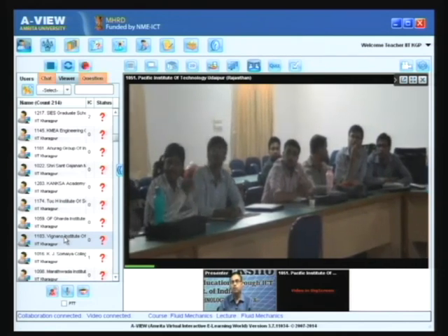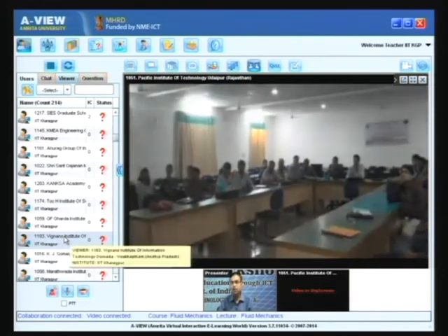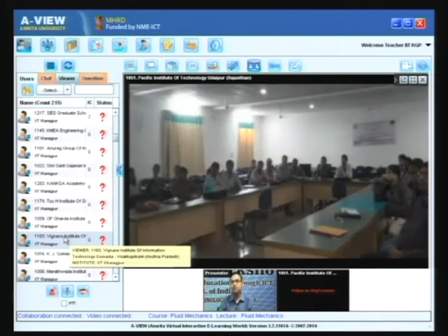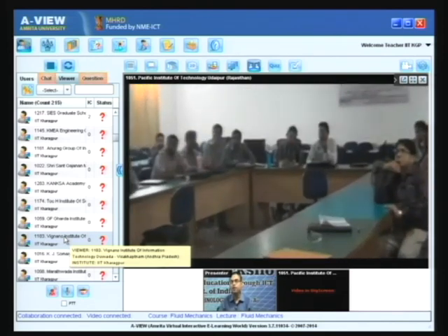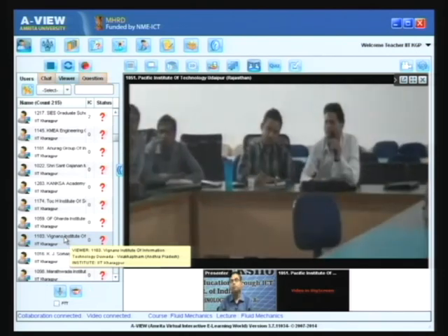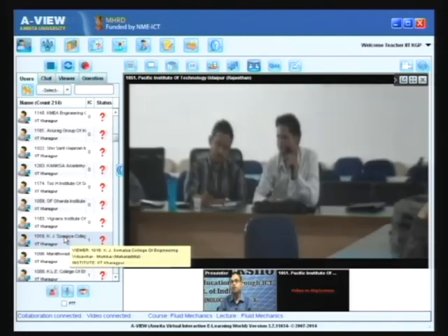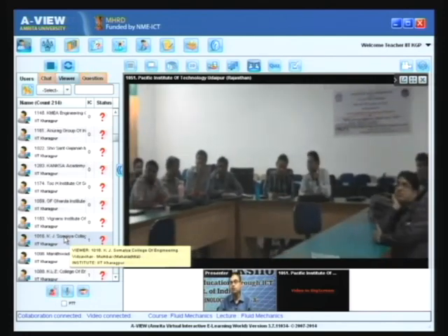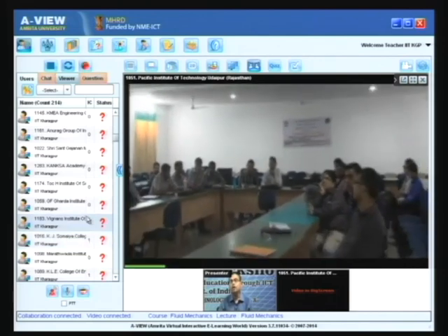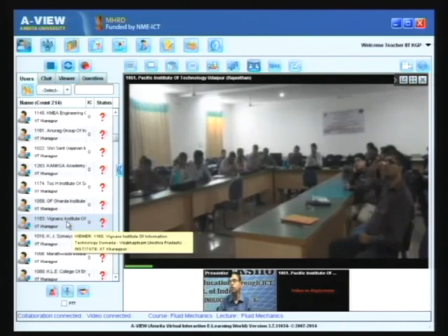So you can write it as k into gamma dot to the power n minus 1 into gamma dot. That k into gamma dot to the power n minus 1 has the unit of viscosity, so you can call it apparent viscosity, but it is not viscosity in a strict sense because it is not a Newtonian fluid. Viscosity is not defined for a non-Newtonian fluid.